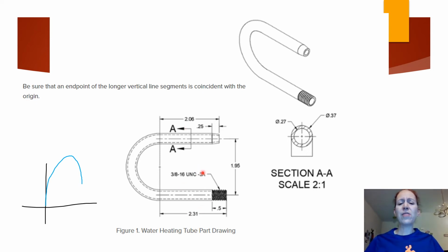Okay, then this is the part that causes a problem. You'll notice that it is tapered here, but there's no dimension given for the taper. So we actually don't know how much that is supposed to be tapered. And they tell you in the PLTW curriculum to make the tapered edge by constructing an axis.